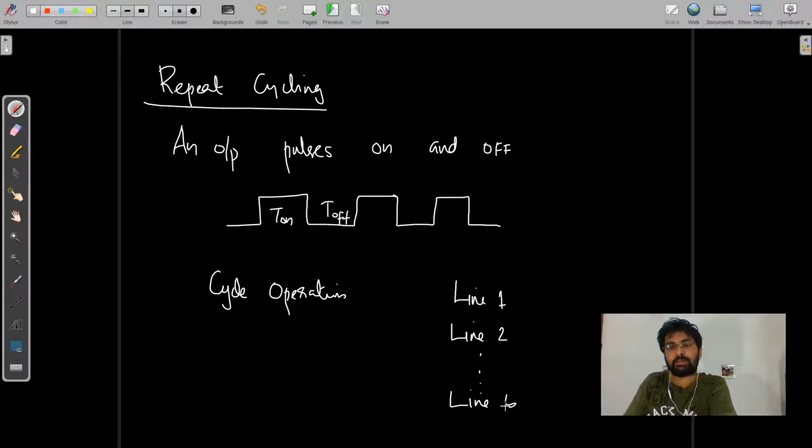Say we have 50 lines of code, and we have to loop this. The looping must be done for continuously executing these lines. In PLC programming, what we use instead of looping is known as interlocking. Interlocking means after executing one line, we switch back to the initial. That is what is known as interlocking. So here also we need some interlocking. Let's see how the interlocking can be done.